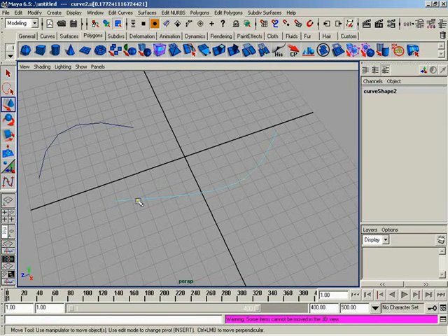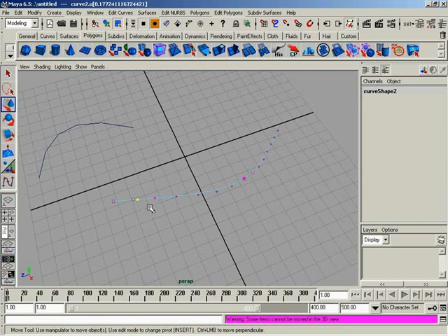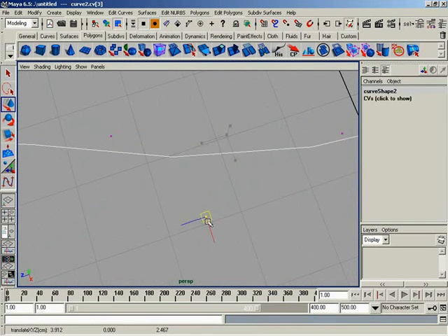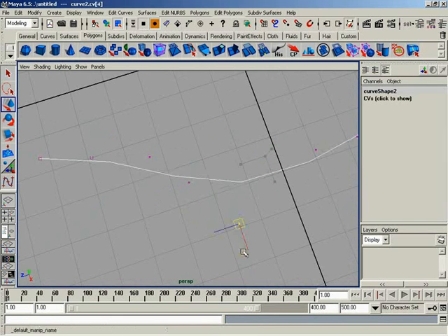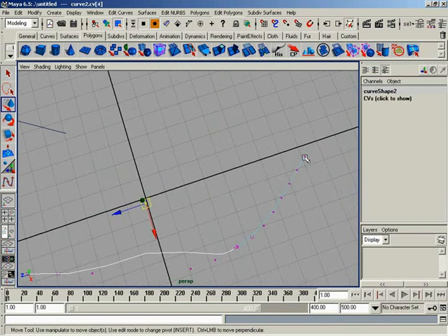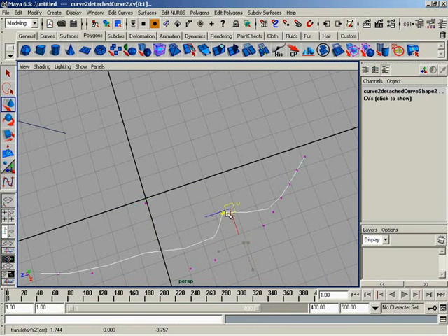Simple enough. Okay, so that's pretty much all I wanted to look at in regards to the anatomy of a curve. Just CVs, edit points, holes, and curve points. Just remember, with CVs, they don't lie on the curve itself unless you've got a 1-degree curve, which in that case it only makes sense because it's a straight line. So let's go ahead and switch back over to CVs real quick. So you can see here the CVs, they start to fall off of the curve, especially if I start moving them around, that'll make it a lot more apparent. There we go, like such. You will always have the start CV and the end CV on the curve itself. All the rest, it's a whole different story.